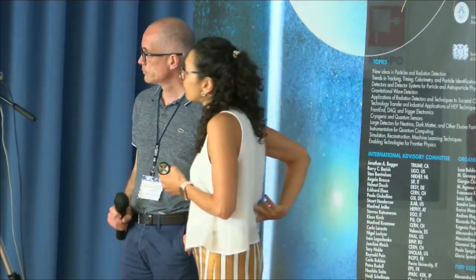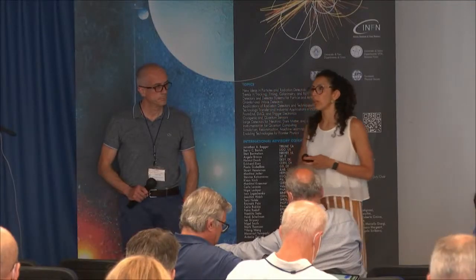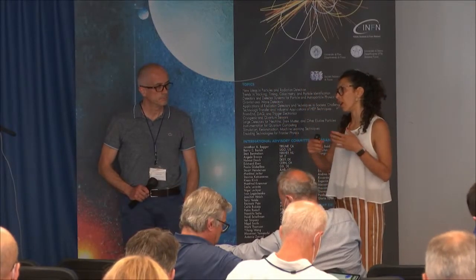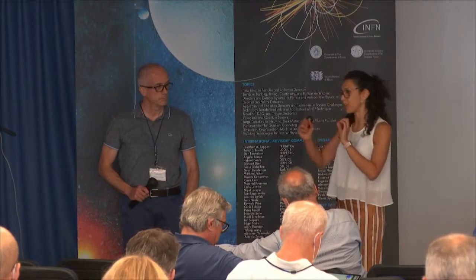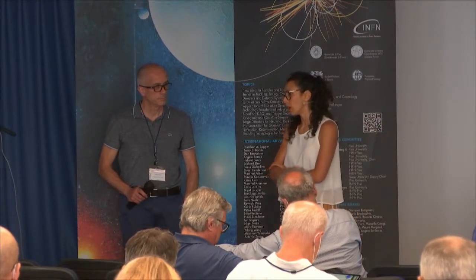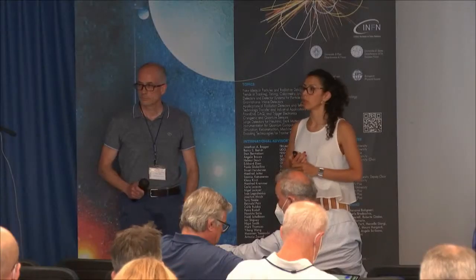Okay, thank you. One last question. You have quite a different data rate in the South Atlantic Anomaly and outside, so you change the prescaling of your trigger to get about the same data rate. Do you pre-program the prescaling rate according to your map, or do you adjust it dynamically, like with a PID loop? No, we adjust it for each orbital zone, because we cannot risk that there is a slight change and then we lose data. So you pre-program it? Yes, for each orbital zone. Okay, thank you.